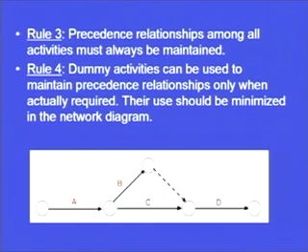So, use of dummy activity is required wherever logic has to be incorporated in the network, but we cannot be too liberal with the use of dummy activities. We have to keep a check that we use the minimal number of dummy activities in the network, otherwise the network will become very complex.